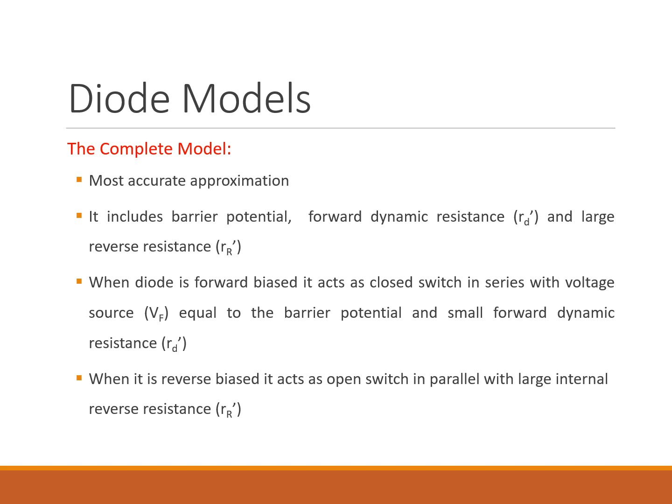In the forward bias behavior in this particular model, the forward biased diode looks like a voltage source equal to 0.7 volts for silicon in series with a small resistance R sub E prime that affects current flow at high currents. And this matters when you're working with fast switches, power electronics, or precision analog circuits. Now let's look at the same thing under reverse bias.